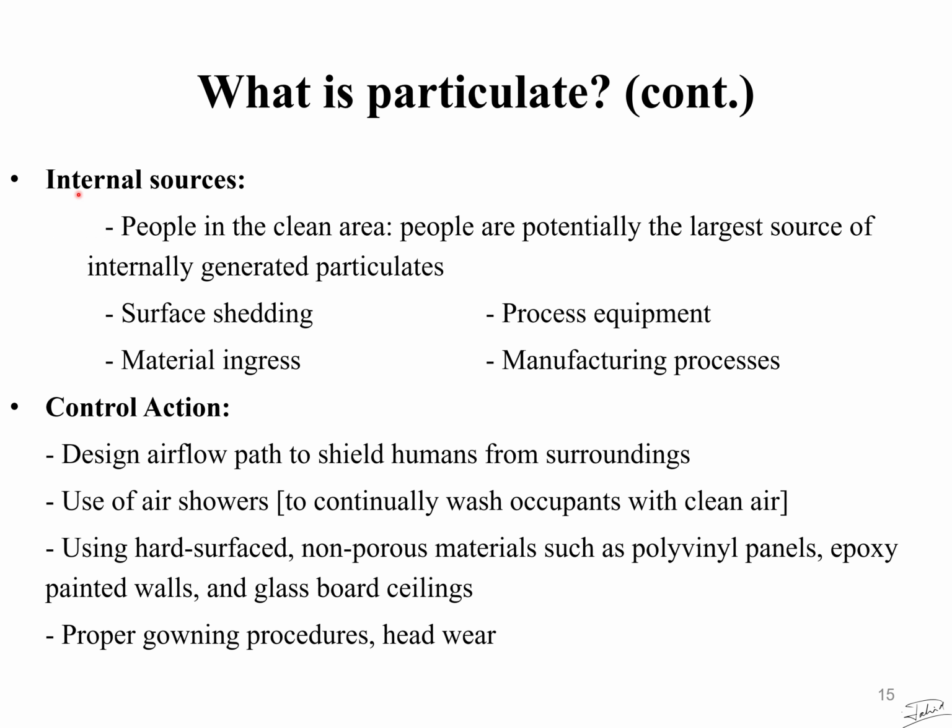In the case of internal sources, people in the clean area are potentially the largest source of internally generated particulates. Surface shedding, material ingress, process equipment, and manufacturing processes are also responsible for internal sources. So how can it be prevented? Design the airflow path to shield humans from the surroundings, use an air shower, use hard-surfaced non-porous materials such as polyvinyl panel, epoxy painted wall or glass board ceiling, then proper gowning procedure, headwear, etc.